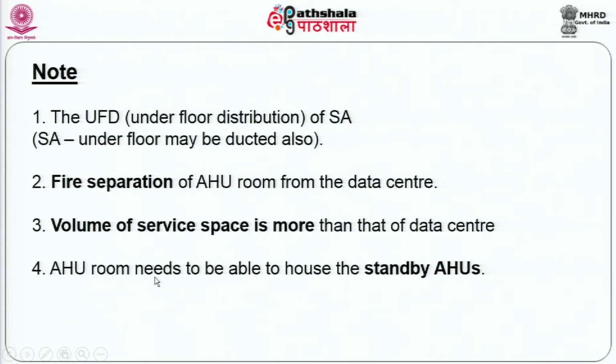It is definitely required to say that a server room will work 24/7 and 365 days in a year. Now, that is possible for that kind of equipment which has been built for that kind of reliability. Air conditioning equipment is not half as reliable as that, but given the best type of equipment that one can go in for, it is definitely necessary to consider that you have standby equipment on your air conditioning. Supposing your total load is met by 4 units, it is necessary to have a 5th unit as a standby, so that in probability if one unit fails, the standby unit can take over its job.